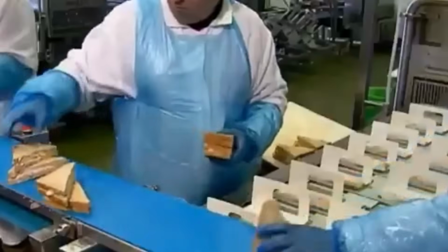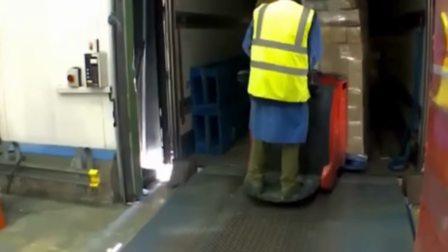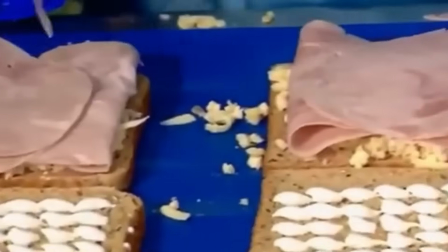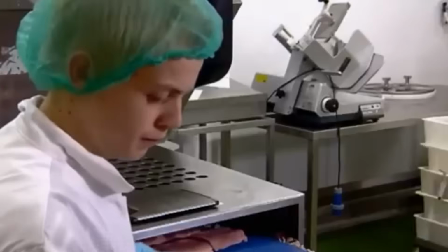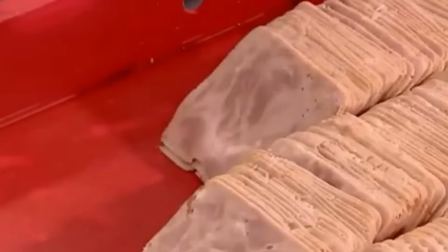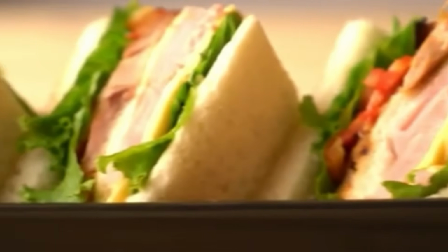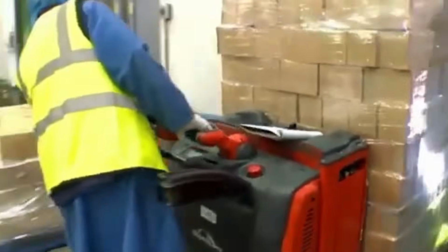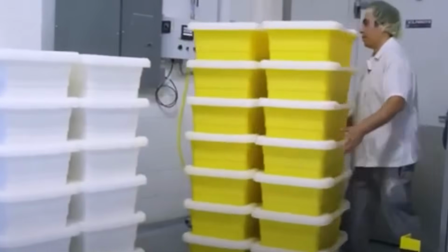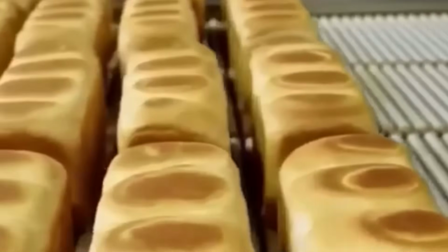Once wrapped, the sandwiches are grouped for boxing. A case packer counts the products and loads them into corrugated cartons, aligning each stack for minimal movement during shipping. Cartons are formed automatically from flat blanks fed into a forming station, sealed with hot melt glue or folded tabs, and labeled on the fly with barcodes, lot numbers, and shipping data. Each carton is scanned and weighed, and any deviation is flagged for inspection.